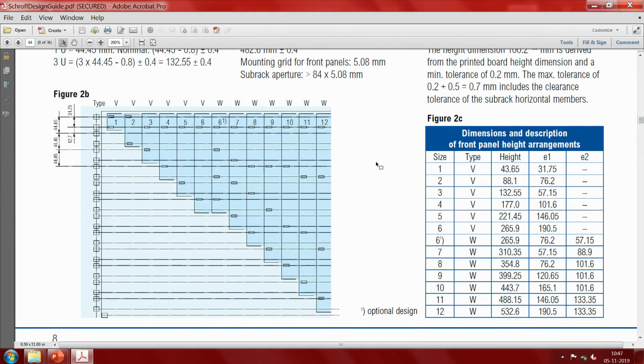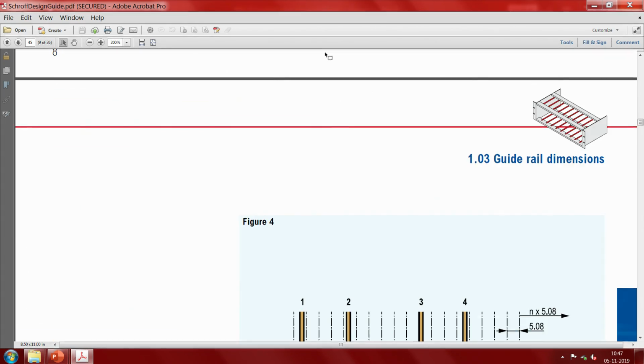looking at one of these tables. And if you remember, somewhere I showed you there is a captive nut. Though the openings there are shown as circular, actually all the professional racks come with a square punch here. You have to push the cage nut inside. Once you push the cage nut inside, you have enough float and everything, happily.